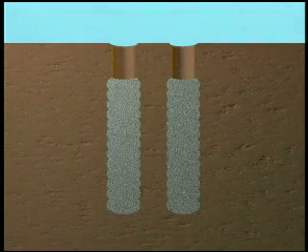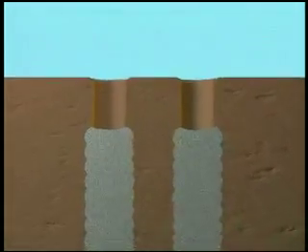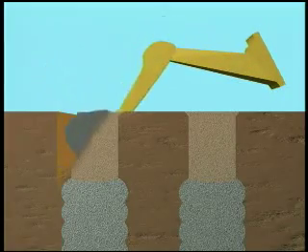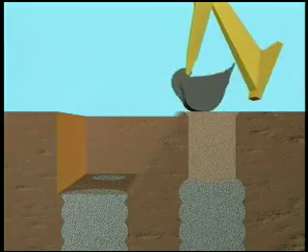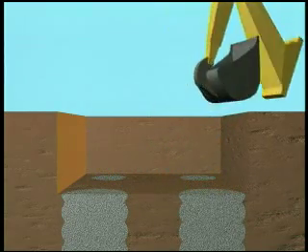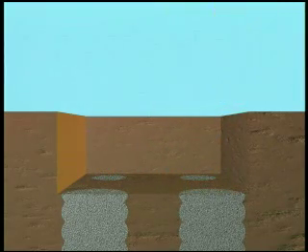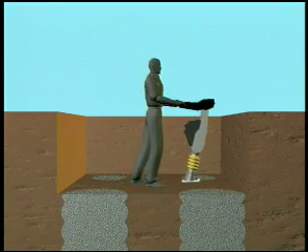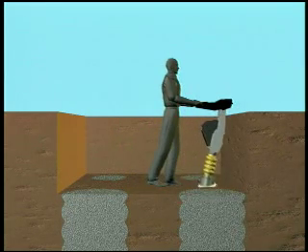After the Geopier rammed aggregate pier is installed, the installer normally fills the void above the pier to the ground surface with some of the drill spoils to protect it from future precipitation. Later, the footing or mat is excavated to the pier top, usually cutting off several inches of pier that was purposefully built several inches higher than required. Although the pier is highly densified and made of durable aggregate, the excavation process loosens the upper several inches of the pier. For this reason, it is essential to compact the top of the pier and bottom of footing with a mechanical jumping jack type of handheld compactor.